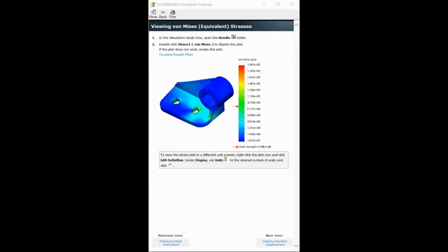That's the component. That's the kind of von Mises stress this thing shows, just to make you guys aware. Those green areas are the parts I was talking about. It's telling you exactly when it's past the yield. And this uses the distortion theory.